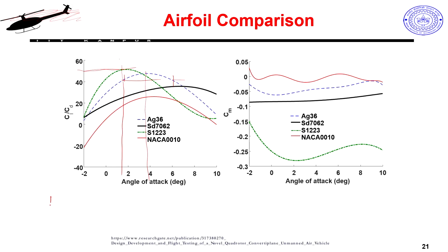So, if I am traveling faster, would my UAV operate at a lower angle of attack or a higher angle of attack? Let us try to understand which one would be the case. So, my lift should be equal to what for my UAV to do a steady level flight? Weight, right. If I draw a free body diagram of my airplane, let us say this is my airplane from the front view, and this is the lift acting on it, it must balance my weight, right, to ensure that it is maintaining level flight.